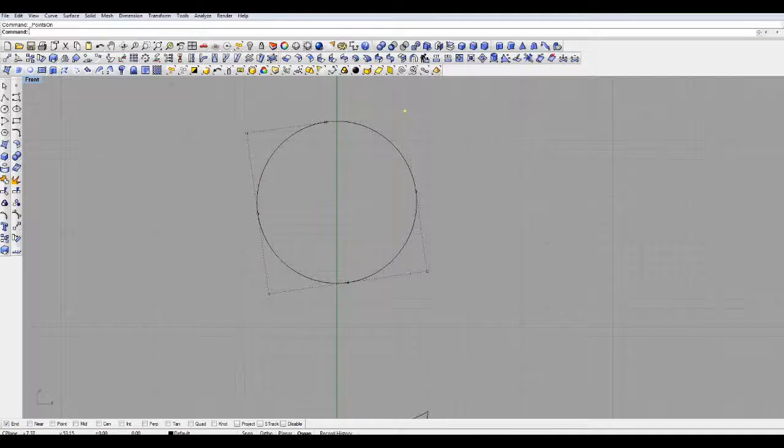And when you click one of these little dots and drag, you can stretch and deform the curve. And this works for shapes, it works for single curves. Anything that exists in this 2D plane has control points. And so, using this, you can drag your shape out and change it.